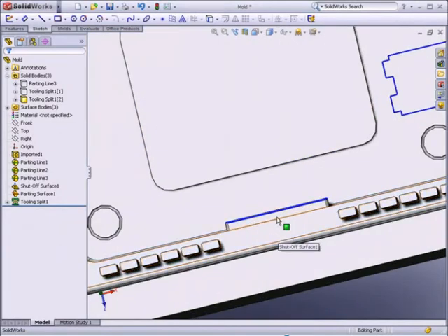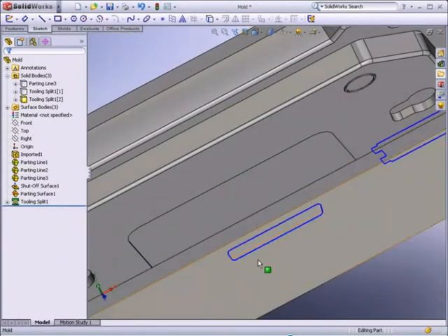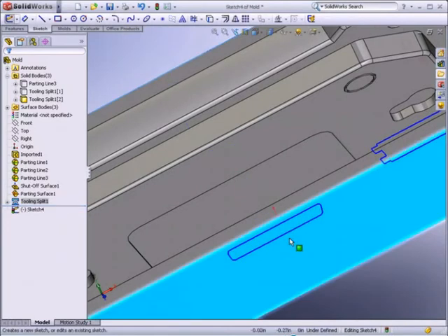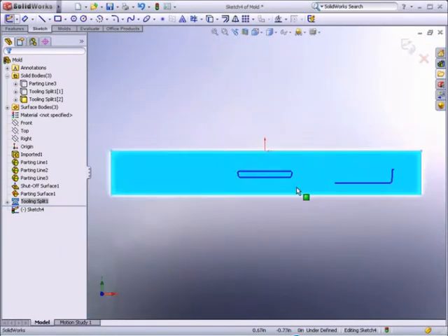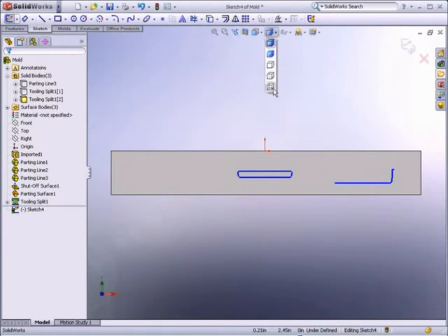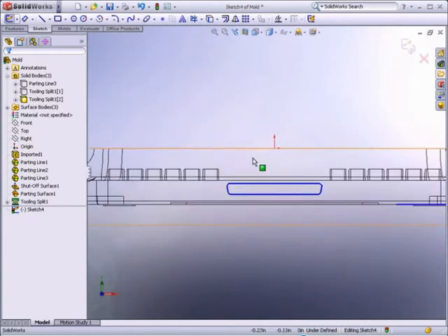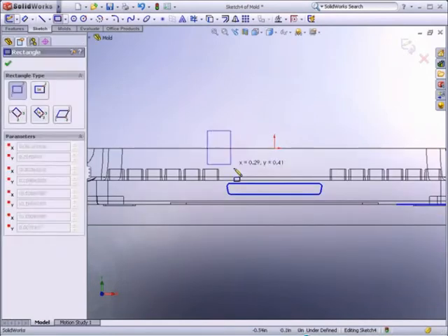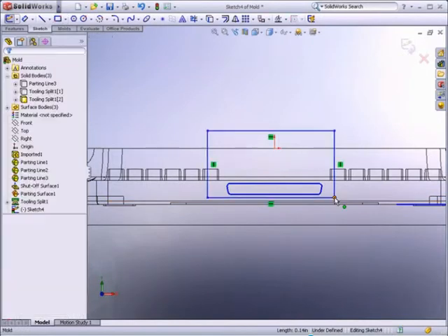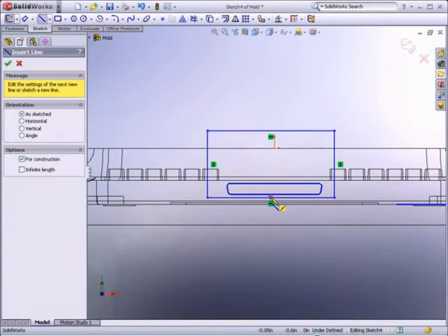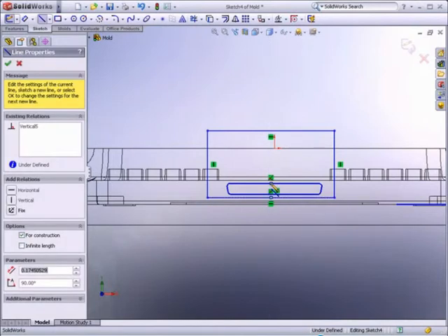On this side of the part, we find an undercut. We'll need to make a side core. By switching to a wireframe display, you can quickly sketch geometry in order to capture and extract the side core from your design. Because everything is sketch-based in SOLIDWORKS, you can easily and quickly create relationships to center the geometry on the side core extraction.